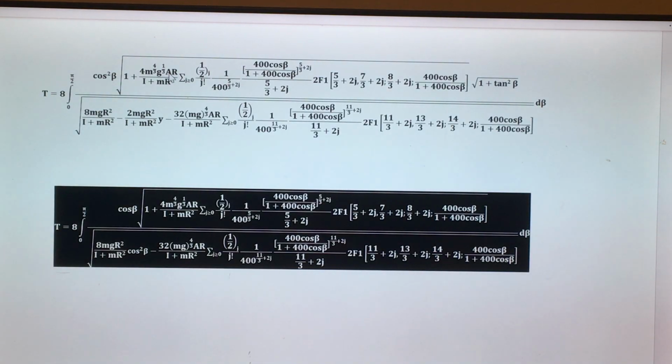You know the values of A, R, M, R. So I is 7 over 5 mr square, not 2 over 5 mr square. It's not the centroidal, it's the other one. You can use the parallel axis theorem for the moment of inertia. And get this one. This is the time taken for the spherical ball to slide down the cycloid, from the top part of the cusp to the bottom part of the cusp.